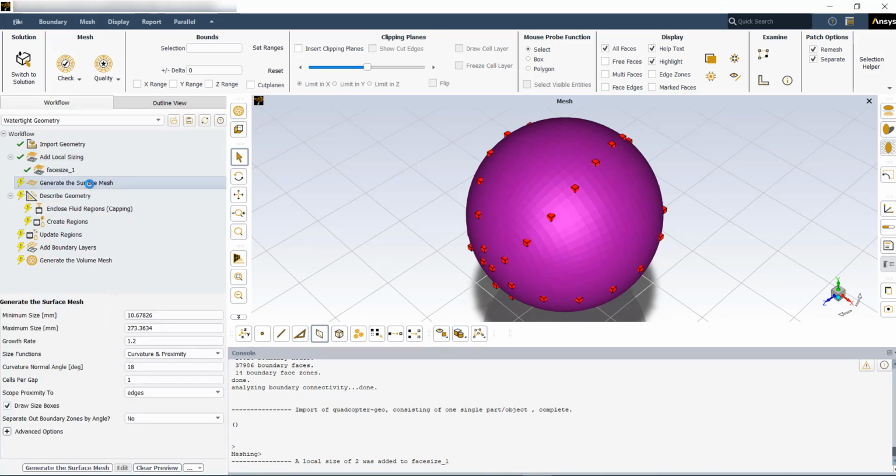The next step would be defining some global sizing. Global sizing will cover the entire geometry for the mesh creation. For the global sizing, we need to define minimum and maximum sizes. Please remember that the maximum face size should be approximately 10% of the cross-sectional spacing for the internal flows. And the minimum size should be small enough to allow resolution of the small features. We can try the minimum size of 2 mm and then the maximum size of 40.